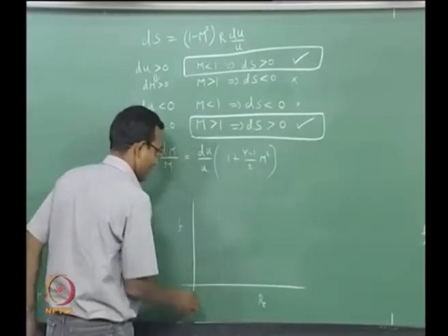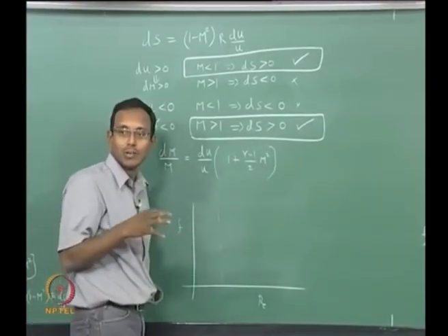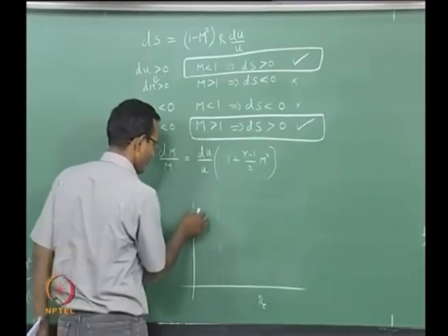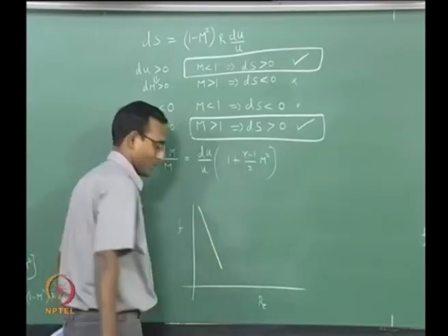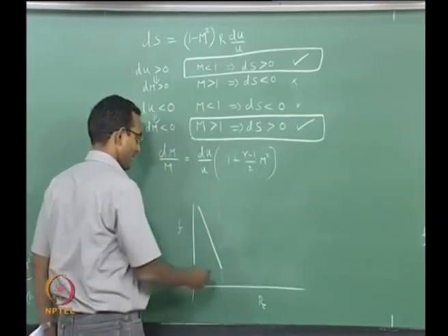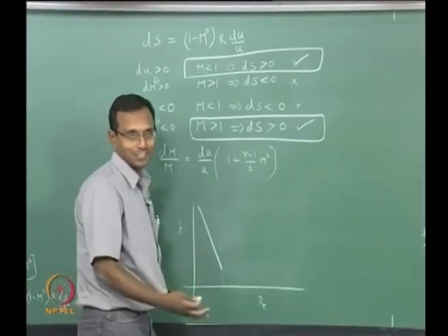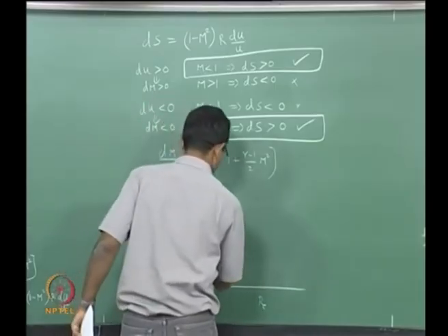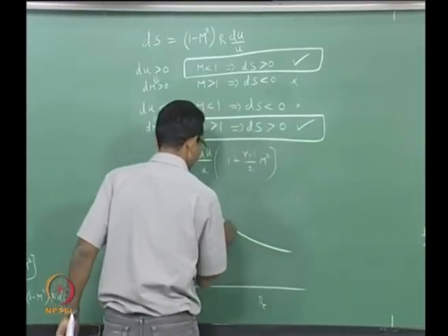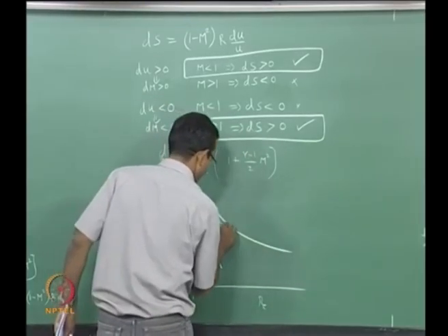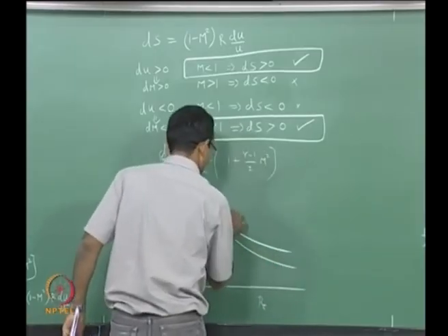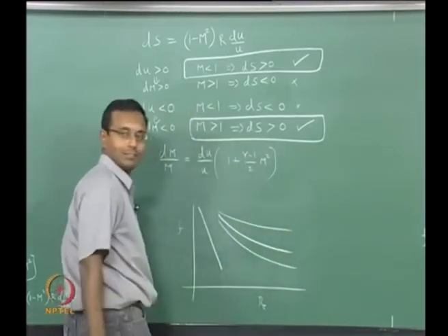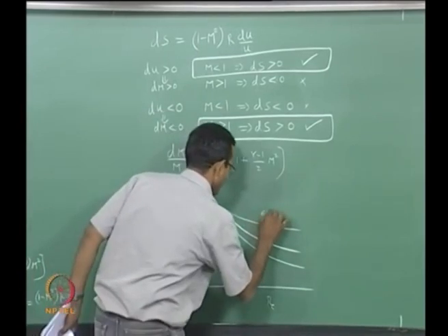For Reynolds numbers less than 2000 or 2300, the transition for a tube, it will just go straight like this and suddenly it will go up after transition because turbulence increases friction, and it is going to go down something like this, and depending on various values of epsilon by D can be any of these curves, each of them is one particular epsilon by D.